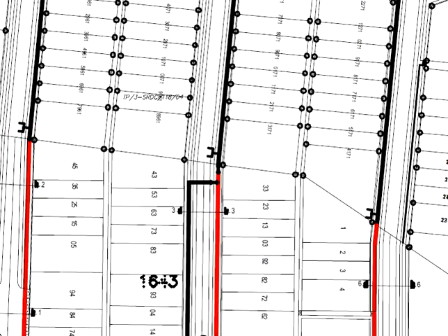That's why normally during the submissions, the water supply agency will require the developer to have the water mains end at the lot boundary so that future development can easily tap the water from the existing mains.